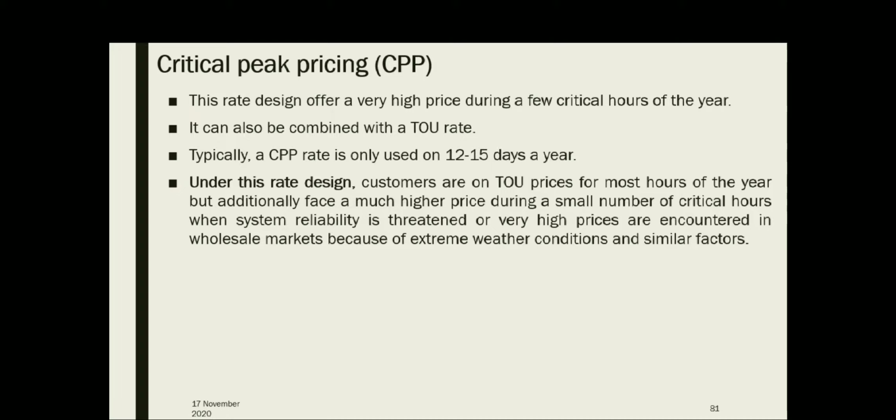This rate design offers a very high price during a few critical hours of the year or hours of the day. It can also be combined with a TOU rate. Typically a CPP, critical peak period, that is a high price period, is only for 12 to 15 days in a year. So under this particular tariff, customers are on TOU prices for most hours of the year. That is the remaining time period.